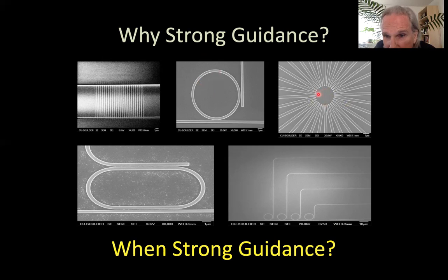Over here, these tips are around 70 nanometers. Again, that's a 1 micron bar. What this is here is a one-to-all multiplexer, or actually a fan out. If I put light in here, it will end up equally in all of these channels in every direction. And you can make them so that they're pretty near equal to within a dB or so. This, I think, is a 1 to 16. We've made, I think, 1 to 64, which has still been pretty good at mixing things up.